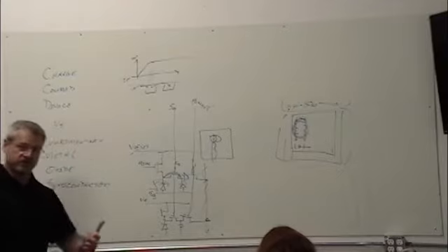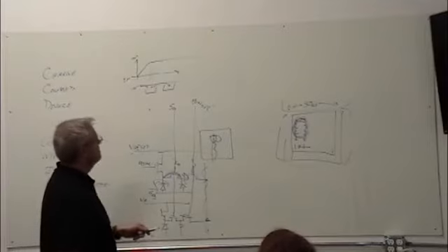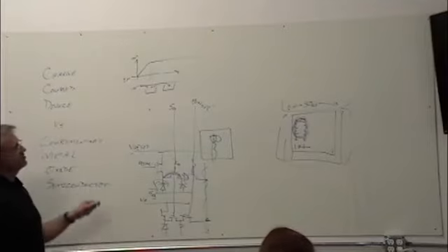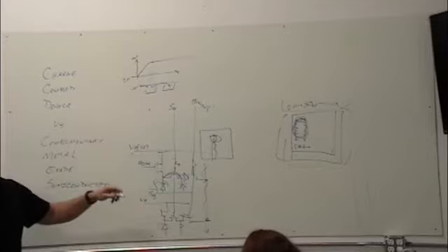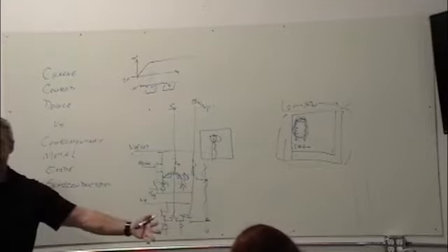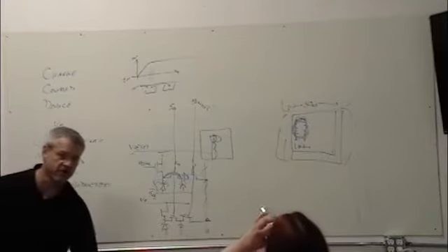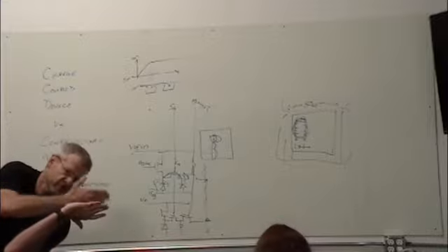Now there's some other neat things you can do. A CCD is real neat because you can do a whole frame transfer, right? I can take all my wells, invert them, and turn them back, and reset the whole thing at once, and it's the equivalent of a shutter opening and closing. In fact, it's better than a shutter opening and closing because the shutter's not coming across my field of view like this.